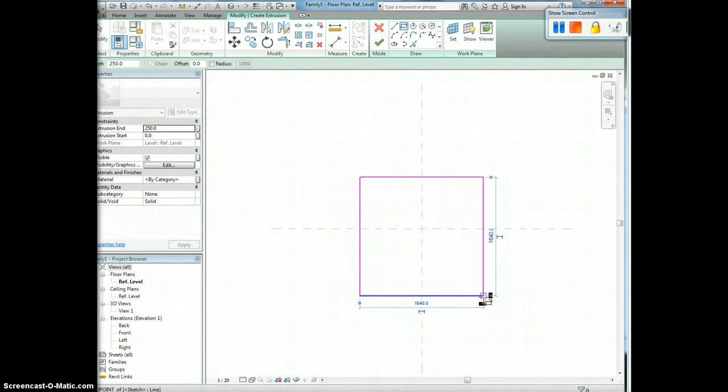The dimension, never mind. You click here, pull down here, click one more time. This is the AutoCAD way of drawing a rectangle. Whether it is centralized or not, don't worry at the moment. Just draw it out there. Later I will show you how to modify all this.